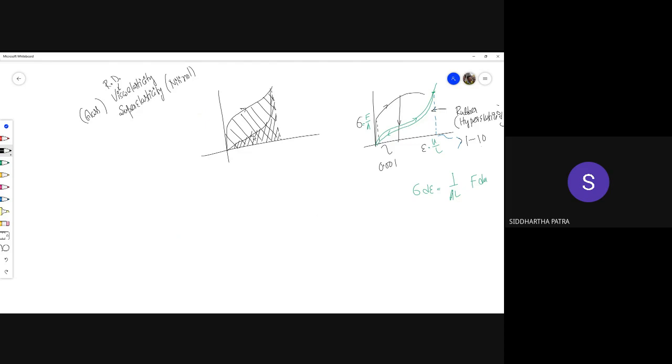undergrad, or rather the school level definition of elasticity, is something we would simply memorize by heart: that elasticity is a property by virtue of which the material regains its original configuration after the load is removed. But that's only the partial definition of elasticity. In order to be true elasticity, it must follow its loading curve while unloading. Then, of course, when the entire load is removed, it will regain its configuration, because it has to come back to origin, which is 0, 0, and zero strain would mean original configuration.